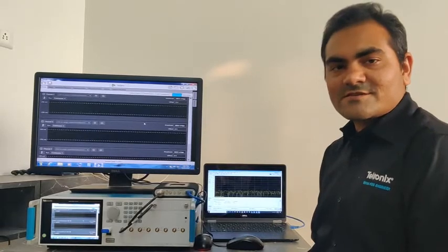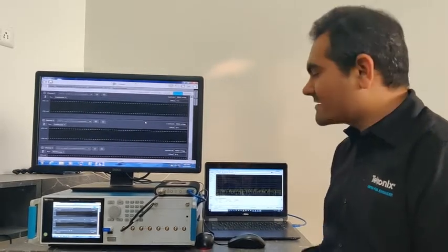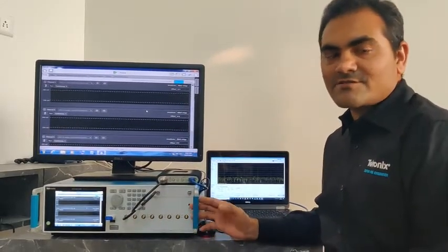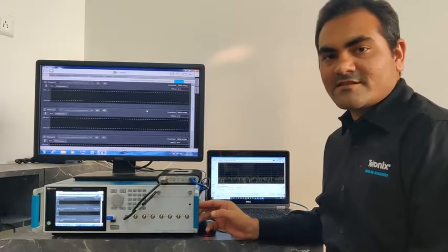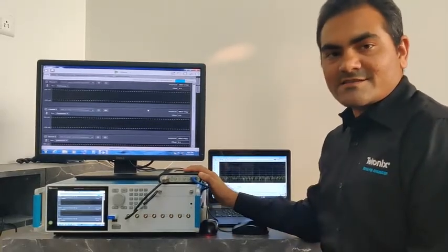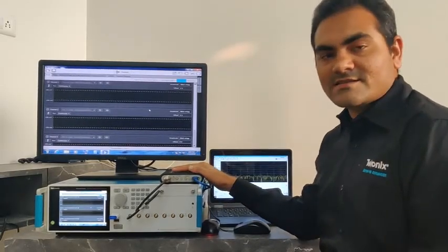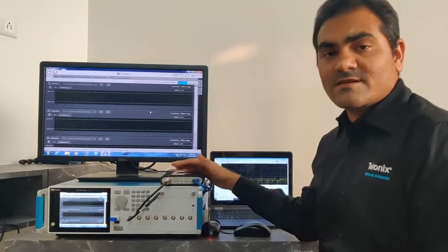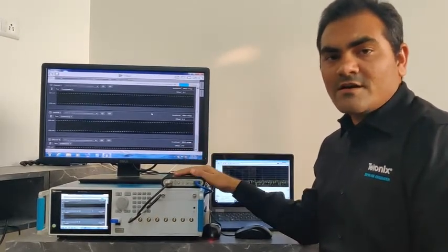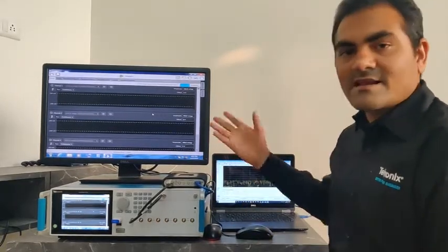This demonstration focuses on a record and playback system. We have here the AWG5204 arbitrary waveform generator, which we're going to use as the modulation generator. And I have a portable USB RF analyzer, the RSA306, with me for doing analysis, and this can also do streaming of IQ data over to a computer. So that's what we're going to do. Let's get started with this.